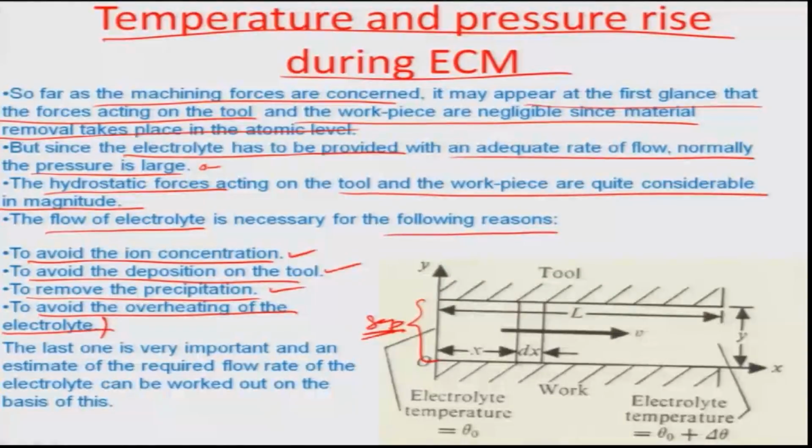Last one, this overheating, and of course the pressure rise therein, is a very serious consequence. It is very important, and an estimate of the required flow rate of electrolyte has to be worked out just because of such a perennial problem which may exist in all ECM setups.